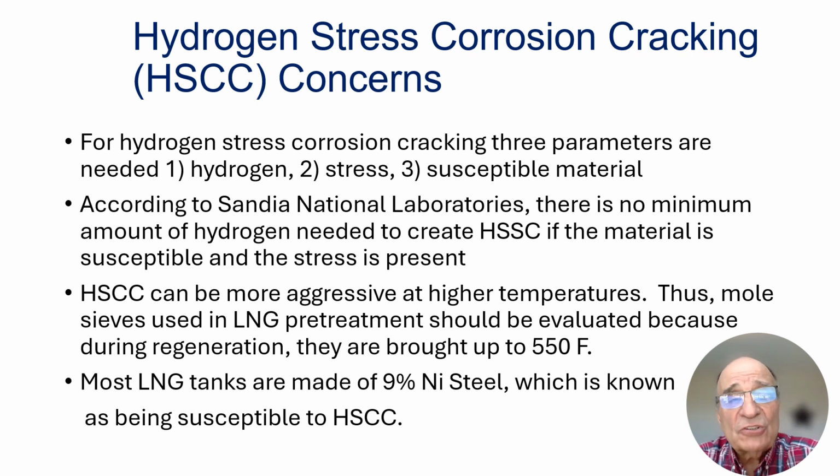Hydrogen stress corrosion cracking is also much more susceptible at higher temperatures. So I think about the mole sieve regeneration vessel in the LNG facility. Well, the mole sieve, to regenerate it, you have to bring it up to 550 degrees Fahrenheit. High temperature, high propensity for hydrogen stress corrosion cracking.